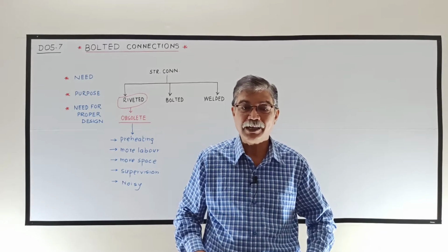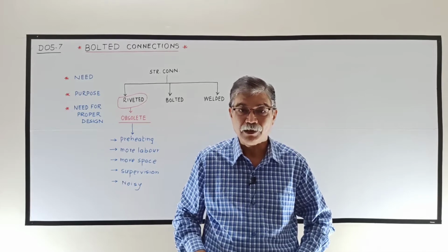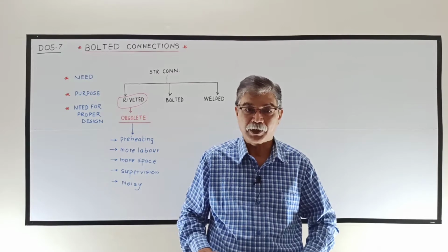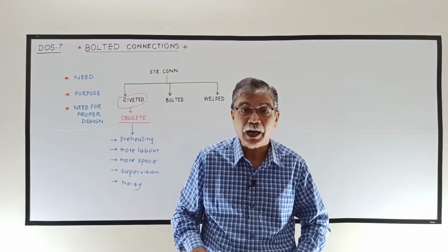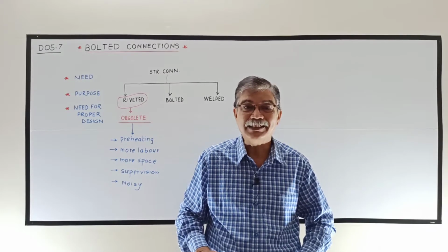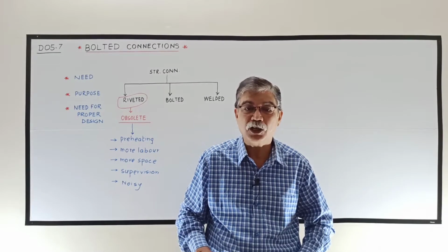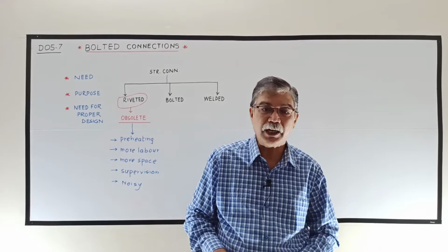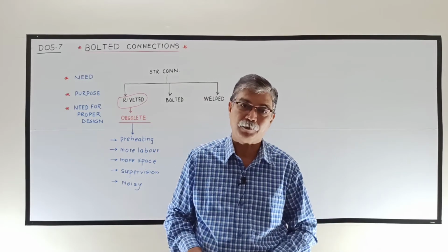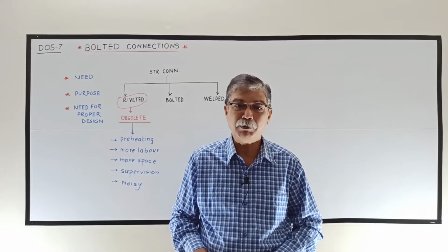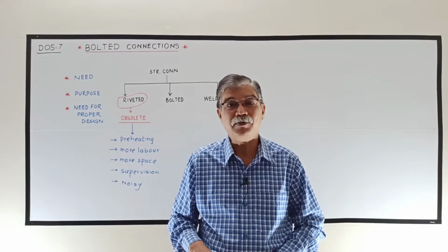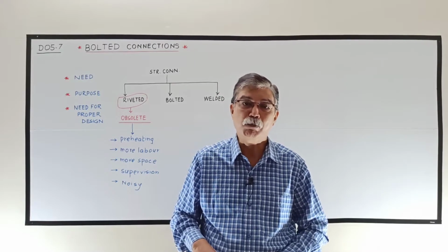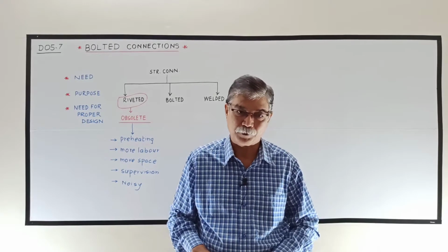As it is not ductile, it is sudden, which does not give any prior intimation of failure, and the failure of connection, as it is sudden, is responsible for the failure of a structure as a whole. For that purpose, the strength of the connection should be more than the strength of the member. If any particular member fails, that can be replaced. But if the connection fails, it will be responsible for complete collapse of the structure.